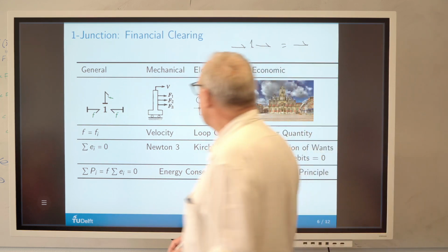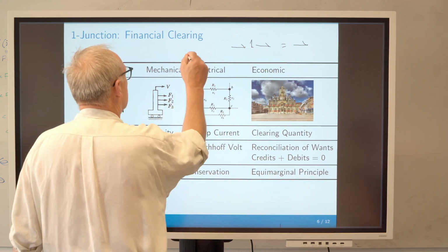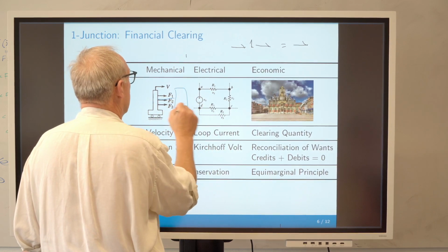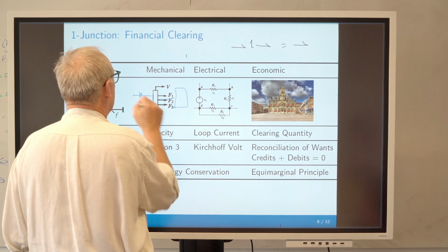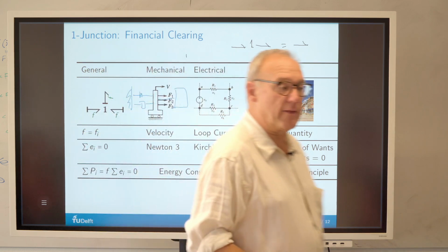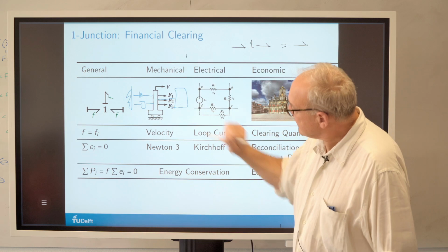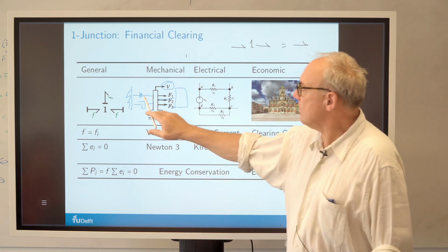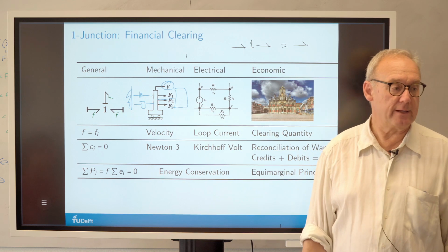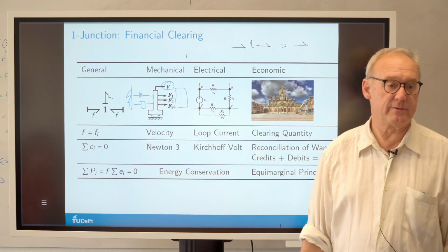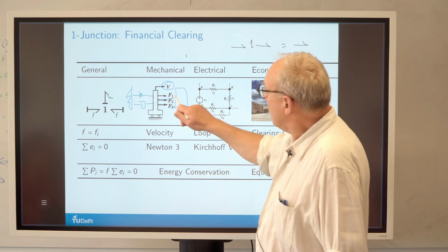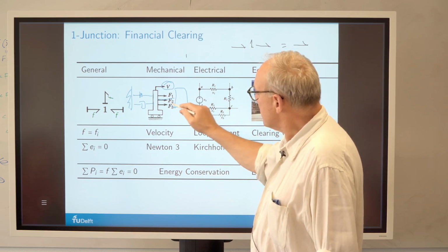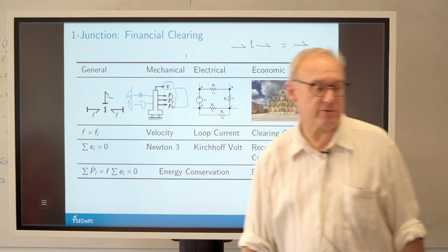If you think of this card, you can imagine your mass spring damper system. The way you would do it, you would attach the mass here, and then say a spring there and a damper there, and there'll be the wall there. So rather than just link them together, you put this little card in there, and what that assures is that you have a place to identify what the common velocity is between the spring, the damper, and the mass. So this is a little massless, completely rigid card. This is the velocity, and there'll be these three forces on there. In this case, F1 might be the inertial force of the mass, F2 may be the spring force, and F3 may be this frictional force.